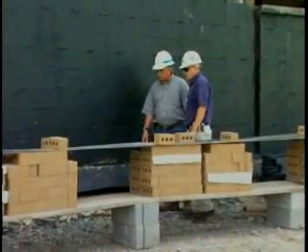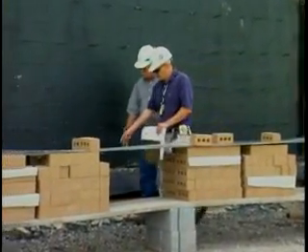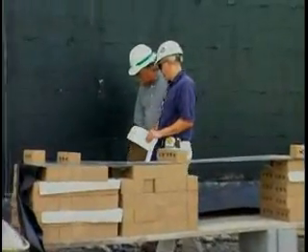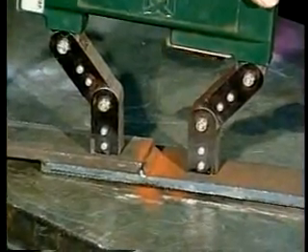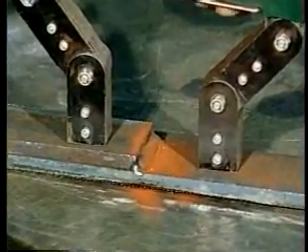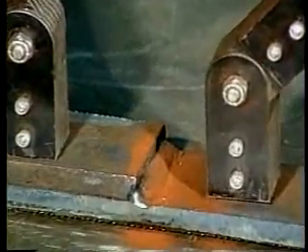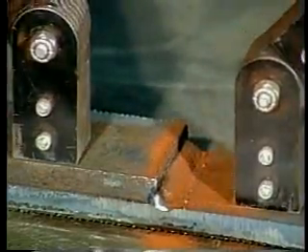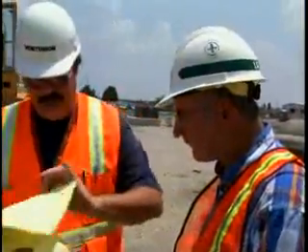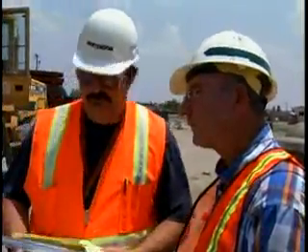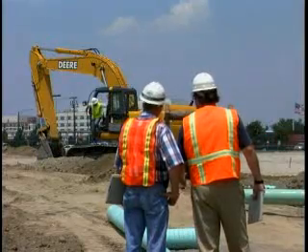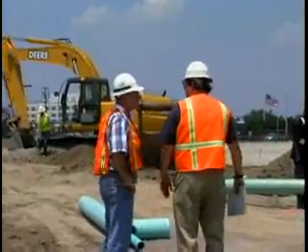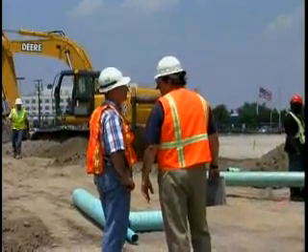Government quality assurance is the method used by the government to determine that quality control is working effectively. The government uses reviews, inspections, and independent random testing to confirm that the contractor's quality control is providing the quality established by the contract. Construction quality management, then, is comprised of contractor quality control and government quality assurance, both aimed at ensuring that the quality established by the plans and specifications is achieved.